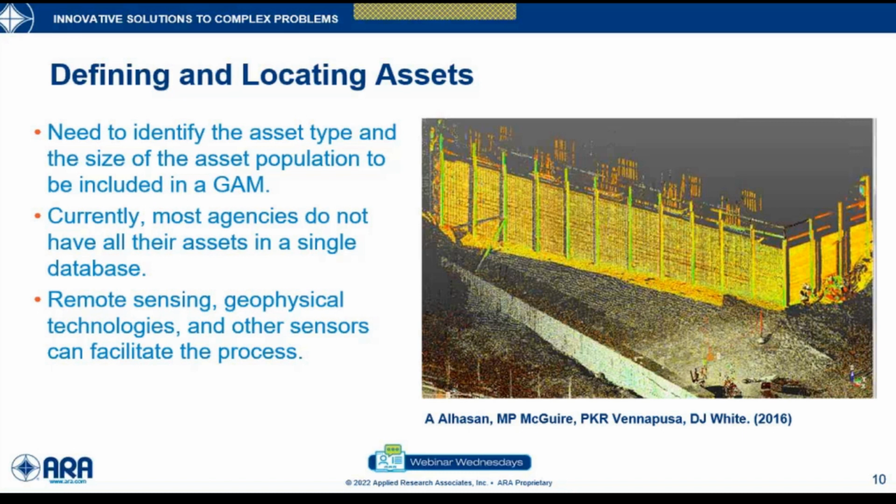Look at the risks associated with these walls. For example, small retaining walls throughout the state that are low probability, but they are extensive in number. So eventually they could fail, and their consequences may not be as dramatic, but from a budgetary standpoint, they can lead to some complications. So risk-based data collection is important.